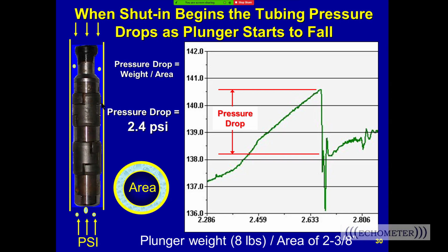Thanks. We have another question from Yula Tang, related to the TAM software, asking if we can load the SCADA tubing head pressure and casing head pressure into the TAM. No, the Echometer equipment is typically proprietary. We only use sensors that we know how they perform. We want to use high resolution sensors to get high resolution data to track the plunger.